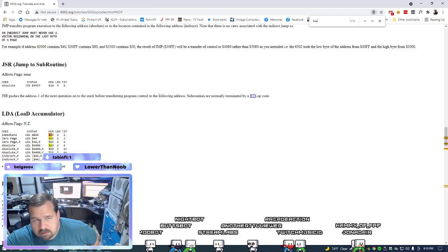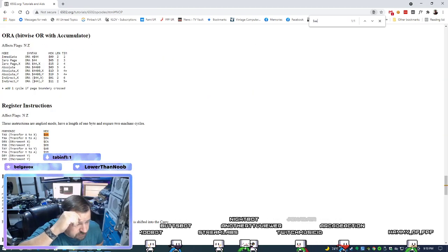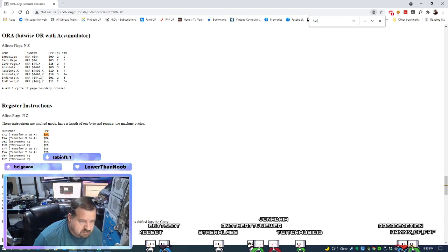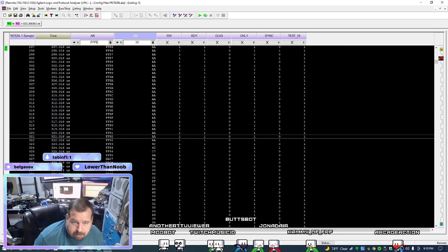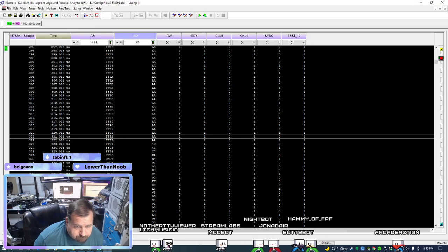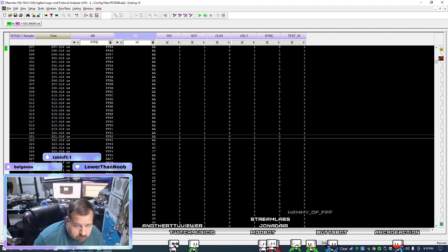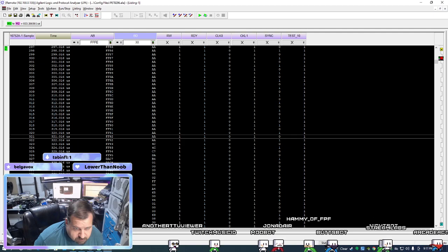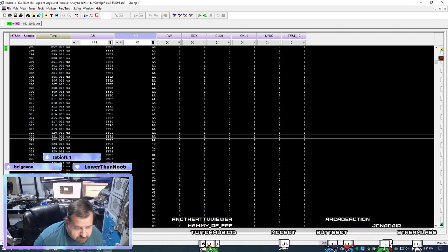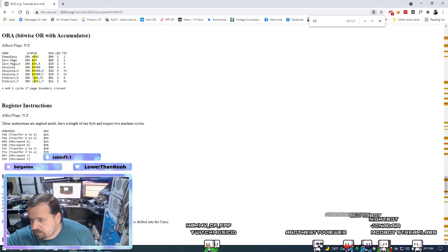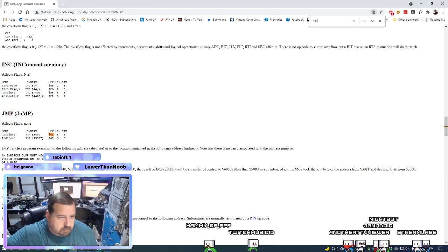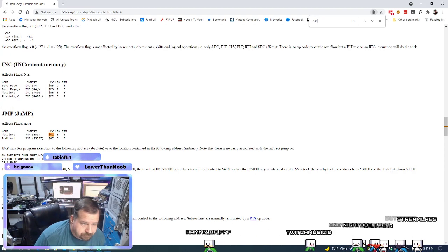What's AA? AA is transfer A to X. That's basically no op. Then it hits 4C. Let's see what 4C is. 4C is absolute jump.